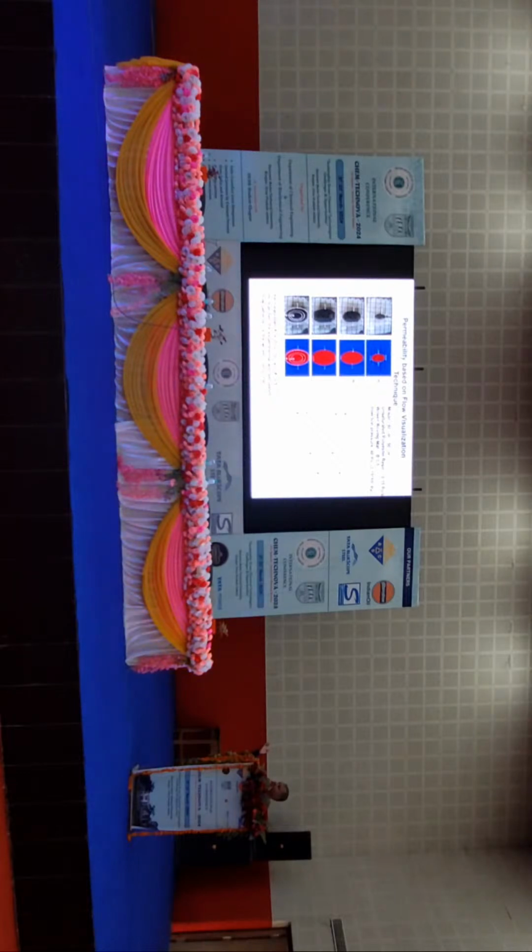So I have conducted the experiment, and the same has been mimicked in the simulation environment also. Because permeability is a directional property, I varied the permeability in the x direction and the y direction, and compared the flow front position at every time frame. When it matched, the permeability values in x and y are taken as the effective permeability.